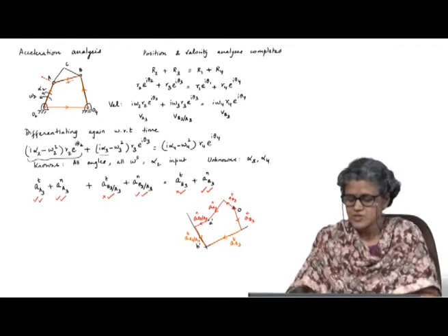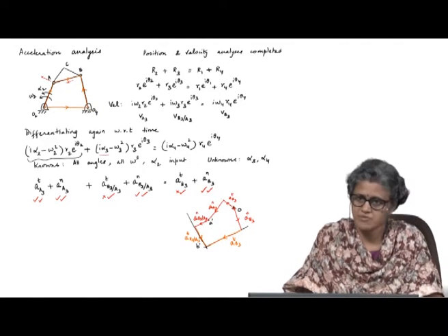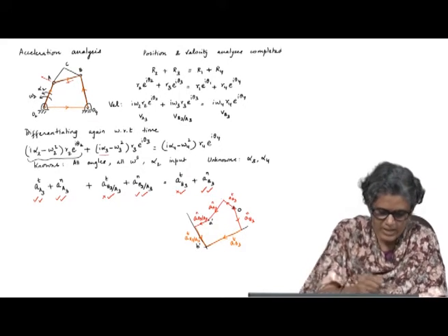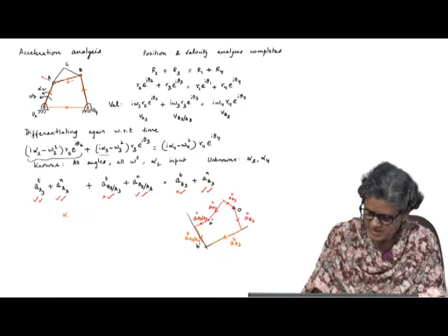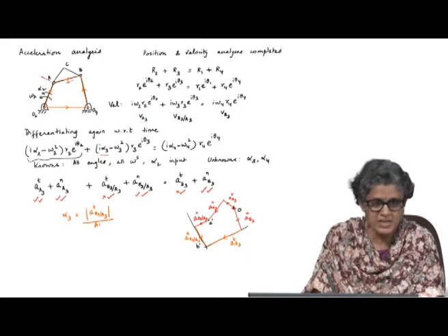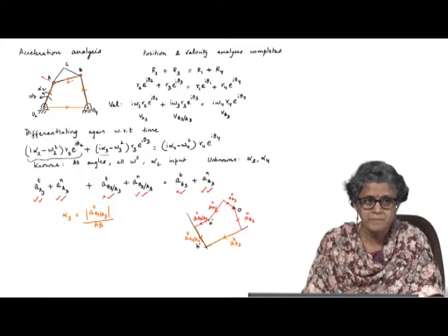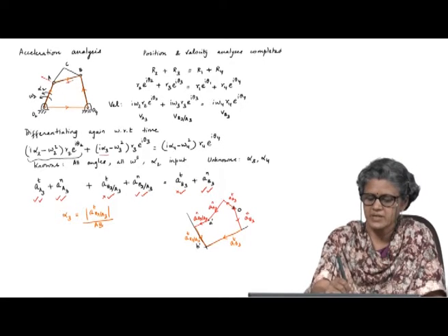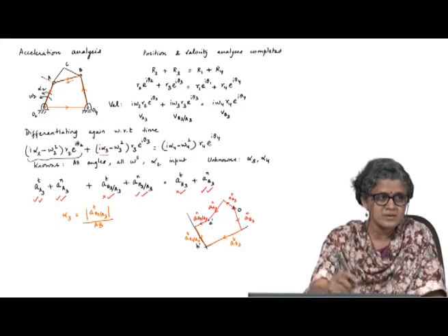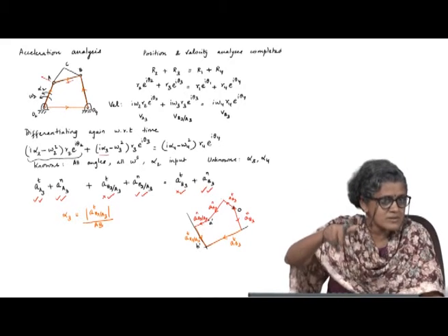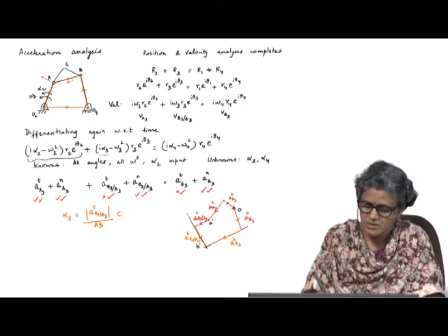So this is, so now from here I have basically solved this vector equation graphically. So now I can find alpha 3 is A tangential, the magnitude of that, by the distance AB, and what would its direction be? So, it is like this, it is perpendicular to AB in this direction, which means the vector from A to B has been rotated clockwise. So, this is clockwise.